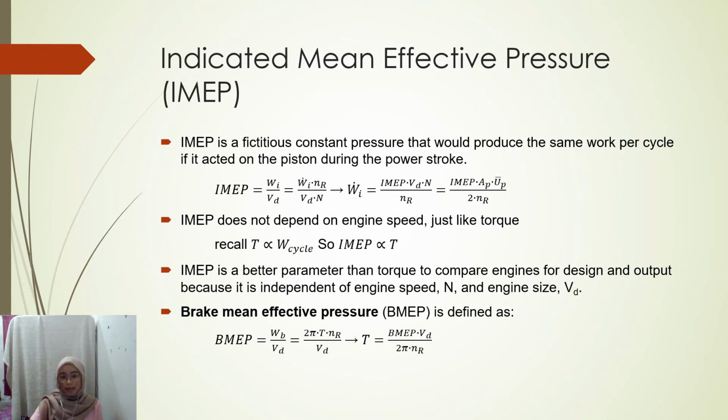IMEP does not depend on engine speed, just like torque. IMEP is a better parameter than torque to compare engines for design and output because it is independent of engine speed and engine size (VD).